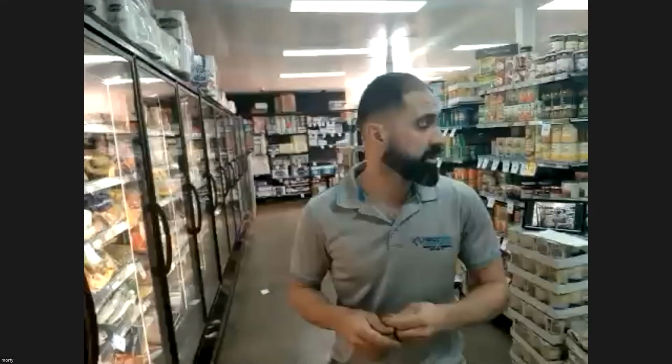Eventually, when the temperature of the room comes down, you'll start to see the superheat narrow down slowly until it matches the set point that you've left it at. The best time to take measurements of the superheat is when the case is at temperature, not when it's 10 degrees or -5. You just have to give it enough time for the temperature to come down and adjust.